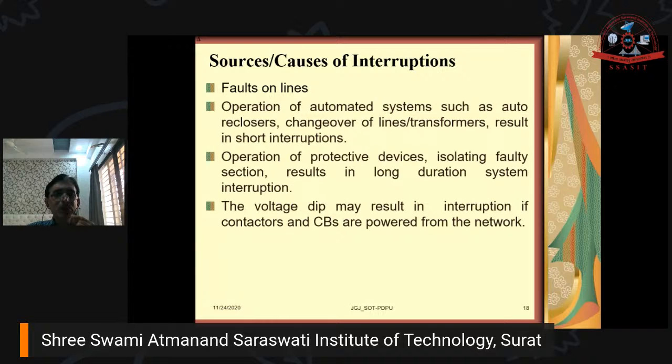What is auto recloser? Auto recloser is nothing but automatic closing of the circuit breaker after its opening. What is the necessity of auto recloser? The auto recloser is provided to restore the service continuity after interrupting a transient fault. What is a transient fault? The faults which are not permanent are called transient faults.